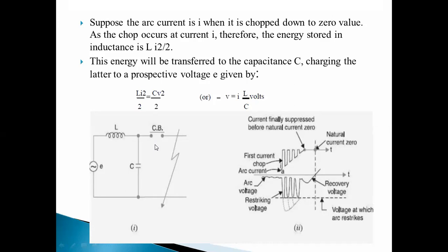There are relays and circuit breakers, and everywhere these are present. Circuit breakers are more than the number of relays, because at each point these are connected to disconnect the faulty section. And here the short circuit is occurring, that is a fault. The same diagram is shown here.